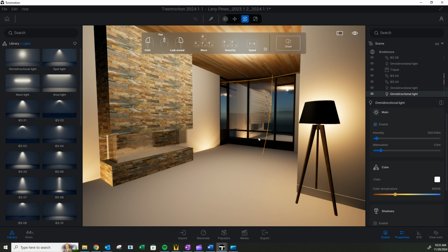But I'm going to back up a little bit. By adding filler light and filling space and making it brighter, it helps eliminate that glare. If you have those center lights, if those are all you have, then it appears more glary to the eye because your surrounding light isn't very much, and you just get that concentrated light source.